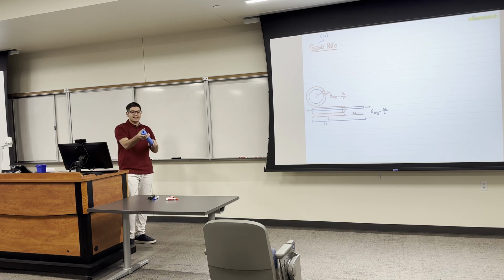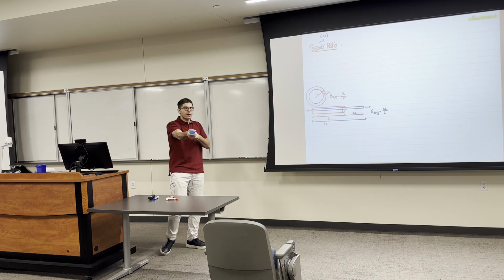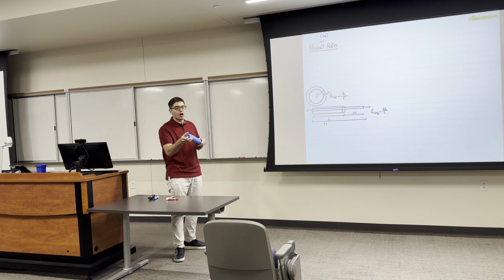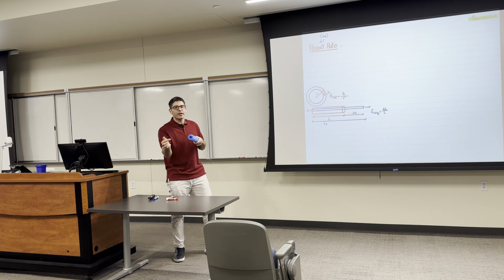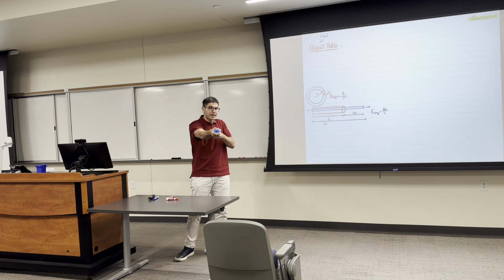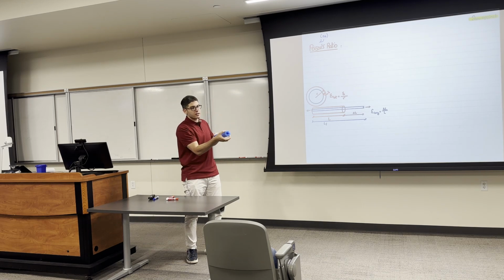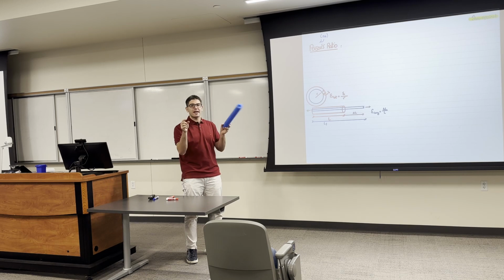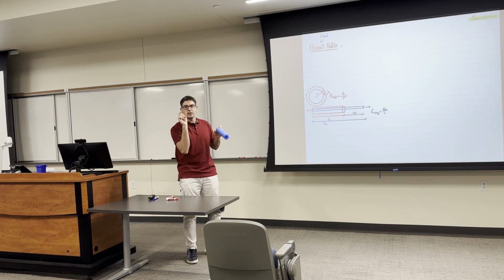When we apply axial deformation here, you all agree with me that not 100% of the elongation goes in the axial direction. However, I have a percentage of elongation that goes in the lateral direction, which is like an explanation to this. When I elongate it this way, this material is going to increase in length and the diameter is going to decrease, which means that there is also a lateral strain.